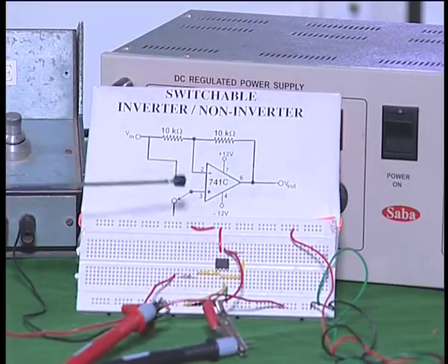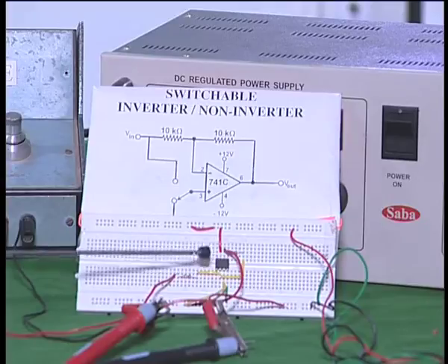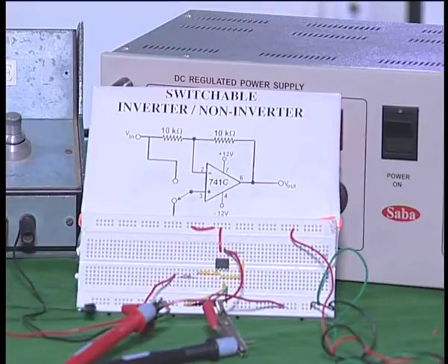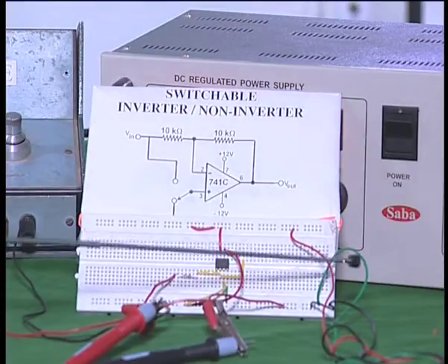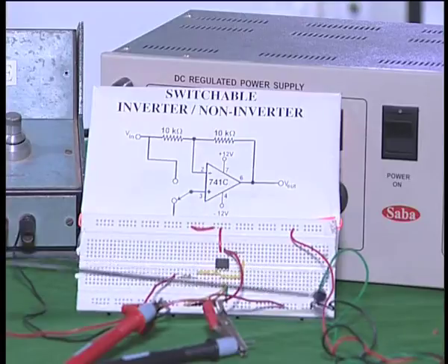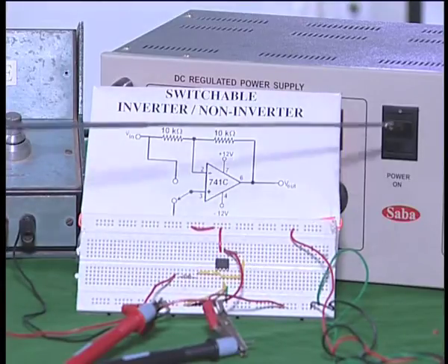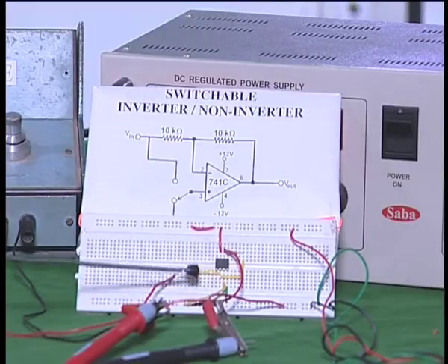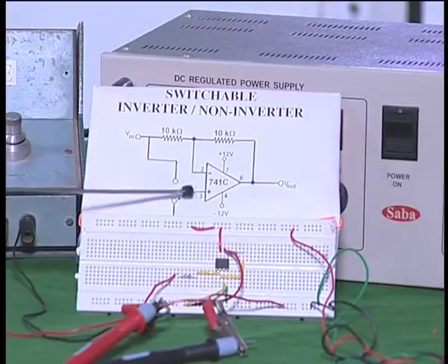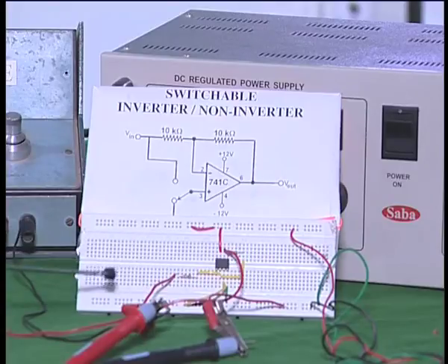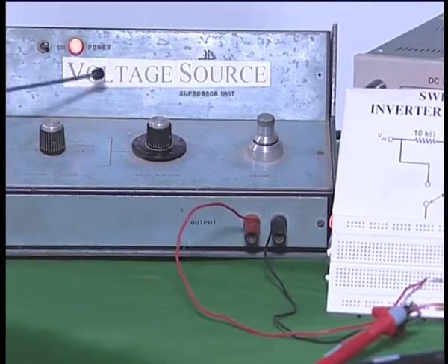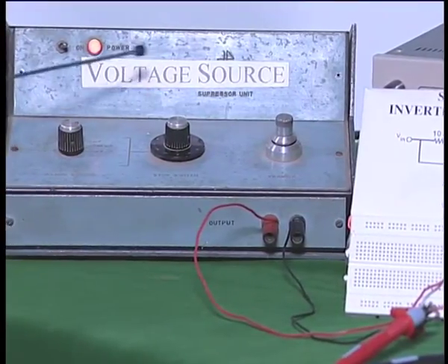The same circuit is wired here. I am sure you can see the operational amplifier there at the center, and this is a power supply, this is the plus 12 volts line, and similarly at the bottom you have the minus 12 volts. The green wire shows the minus 12 volts, and the black wire corresponds to the ground connected to the dual supply that I have at the back. Now, it is actually connected to the ground. This input is exactly in the same way as it is shown in the circuit. It is connected to the ground, this yellow wire, and for the input I am using a millivolt source, which is also very familiar to you. We have used this in the earlier experiments also.